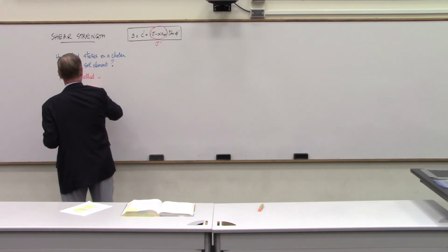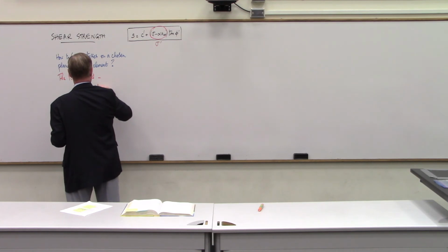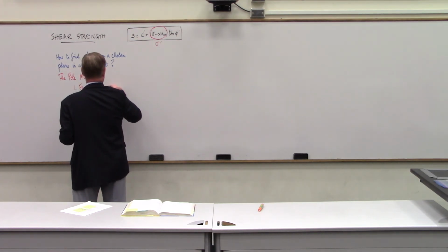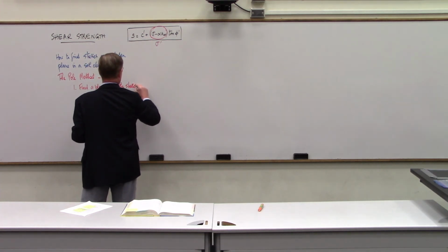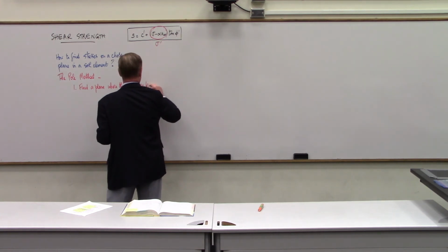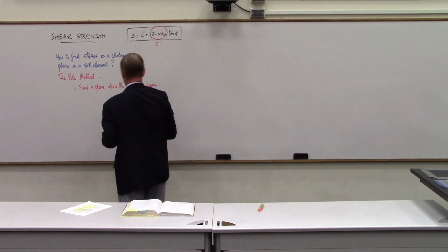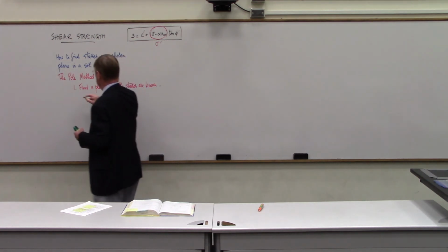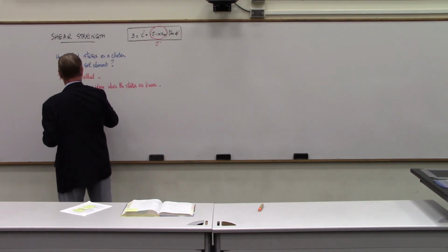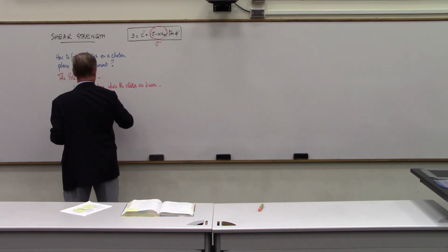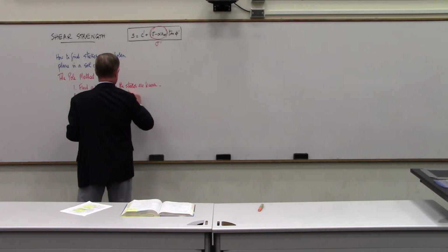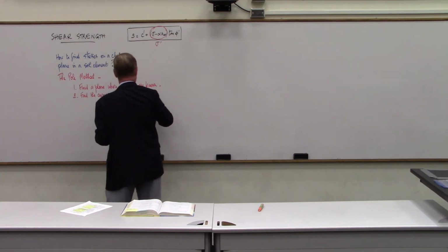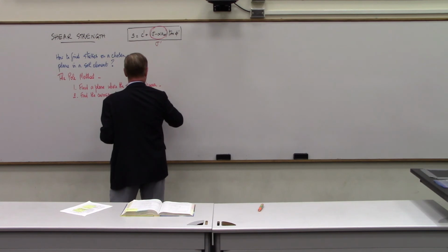So step one, find a plane where the stresses are known. Two, find the corresponding stress points on the Mohr circle.